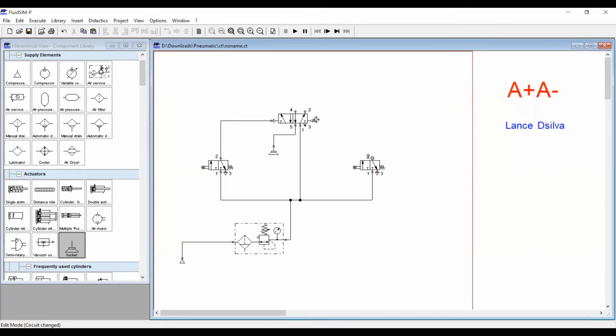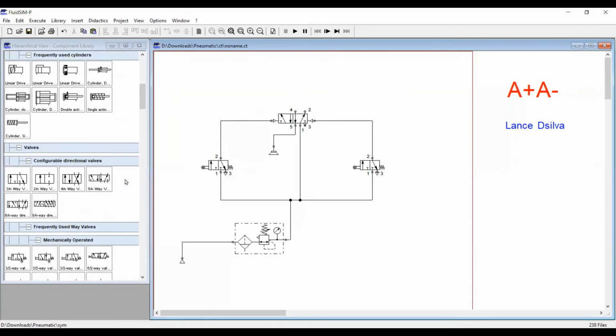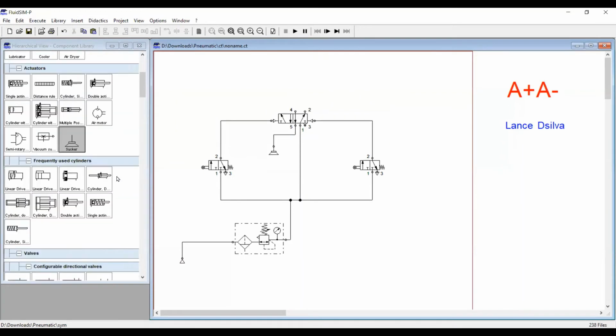Now the last step that we have is the double acting cylinder. Now why double acting? A plus and A minus, we require the piston to go to the right side and again to the left side, so there is a double action, right? So we use the double acting cylinder. In case there is only A plus, then use single acting, or one direction. But in most of the sums, if you are in Mumbai University, always use double acting cylinders. For your practical purpose also, whenever you have practicals in college.